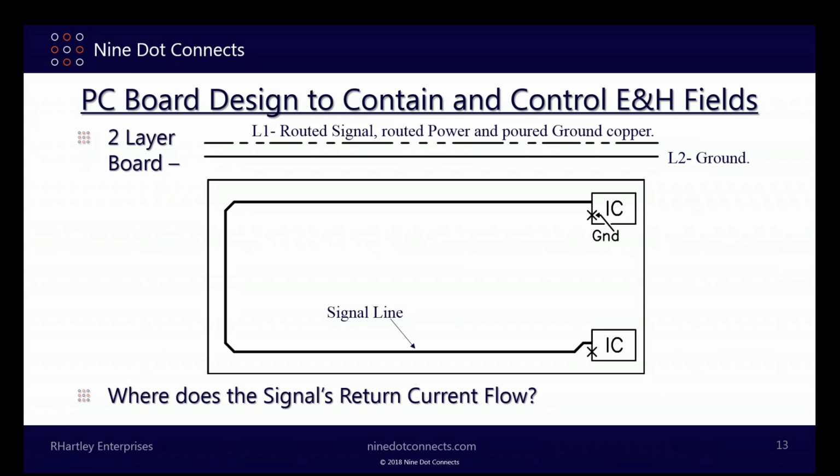If this were a DC signal, pure DC, without even an AC component in the current, that would be the case. The current would take the short path, but it would also take all the other paths across that plane. In other words, at DC, the entire plane would get used as a return path.